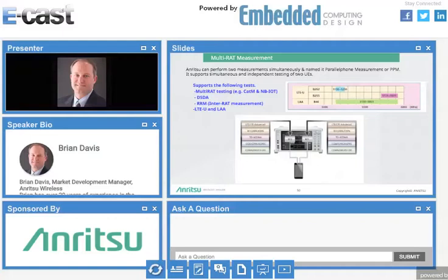Think of it as two base stations in one. It's an option on the equipment where you can have two separate isolated base stations testing different technologies at the same time. So you could be testing CDMA and narrowband IoT on two different devices or the same device. That's the DSDA, dual SIM, dual active, and then inter-RAT measurements too. So say you want to do reselections, redirections while you're doing data, while you're in idle, different ways to move the device through the network. This is especially key in narrowband IoT and CDMA, right? There's not a whole lot of mobility built into those technologies.